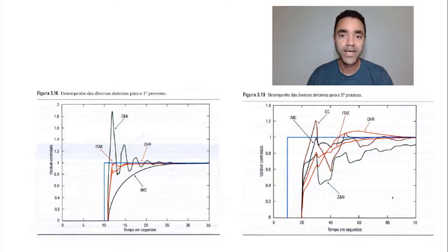In any case, these methods can be useful as a first approach to define the values to add in the PID controller. How easy it is to do that depends on the process, because when we go to the field, we are not dealing with equations, with Laplace transforms, or other kinds of differential equations. We need to evaluate the process, make changes in the controller, evaluate the process again, and based on that define the best values for the PID.